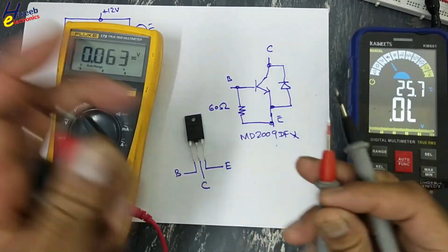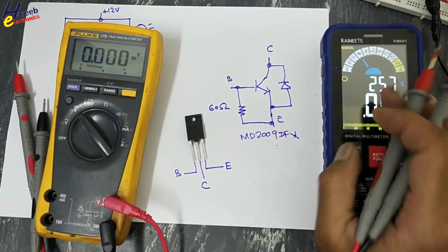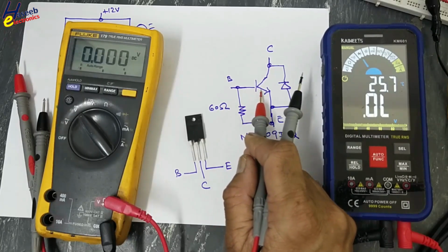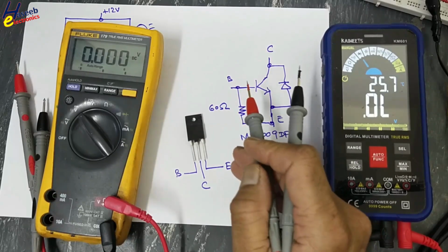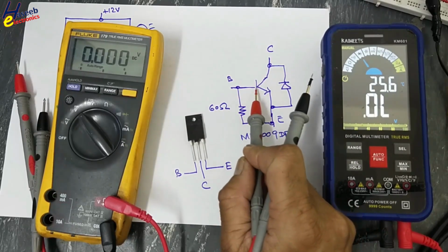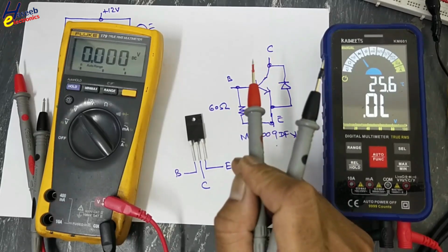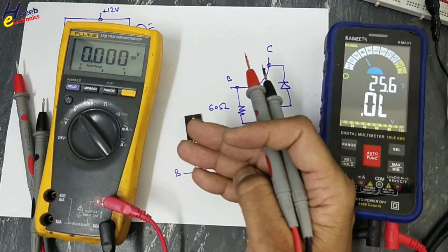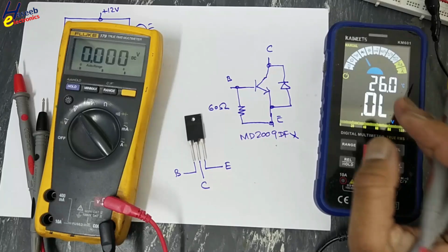Why? If it uses a low value of current, some components will not be tested, because if the current decreases below the junction threshold, it will show open circuit. That is the reason in diode mode, multimeters use high current compared to resistance mode.